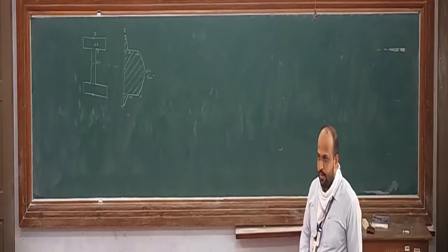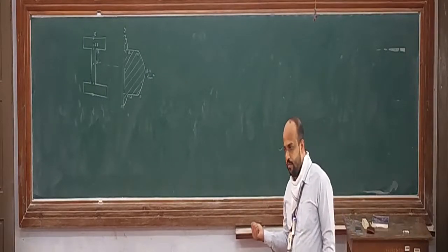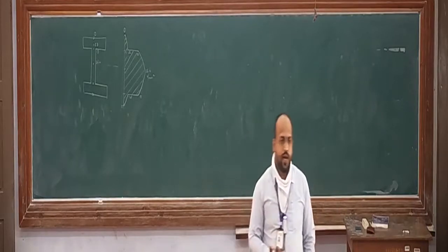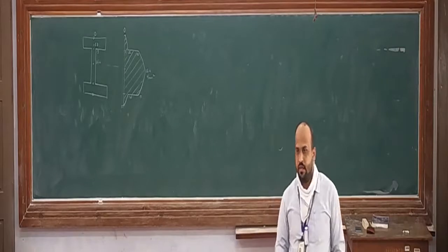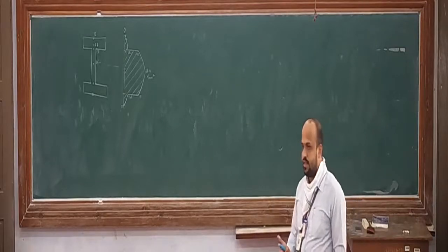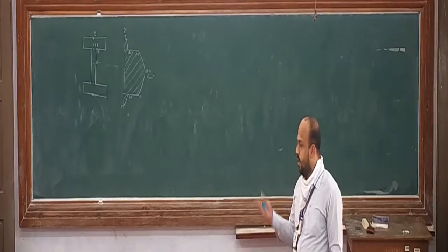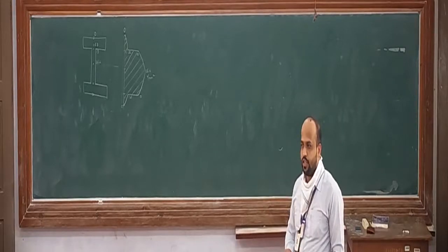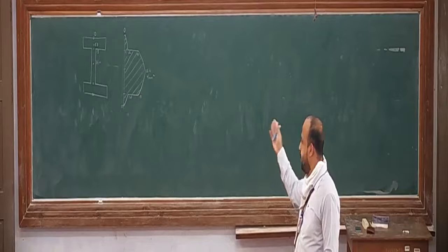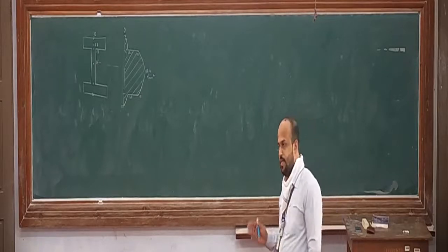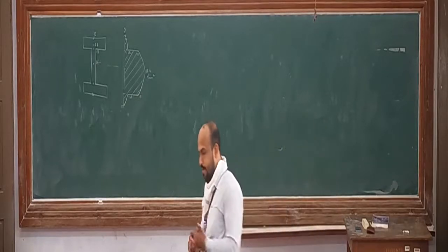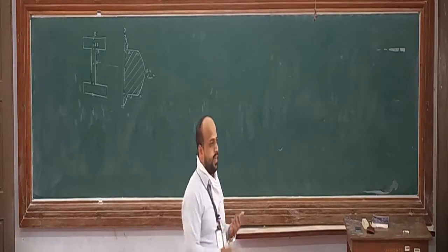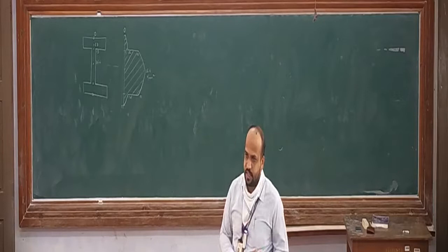You need to find y bar. In the case of bending stress also you need to find the y bar. Then we need to find the moment of shear. Then find the bending stress in the case of bending, and in the case of shear stress distribution, find the shear stress at various locations, and ultimately draw the distribution of bending as well as shear stress. So you can try an I section, a T section, a rectangular section, or any other.